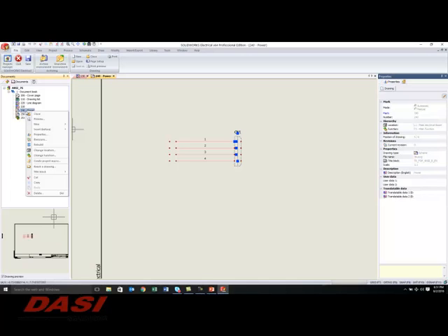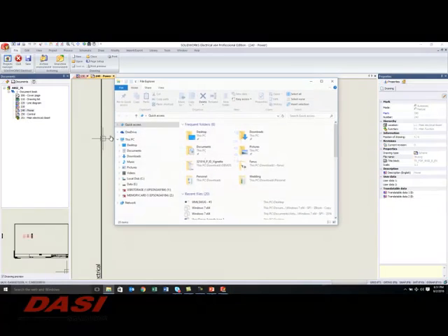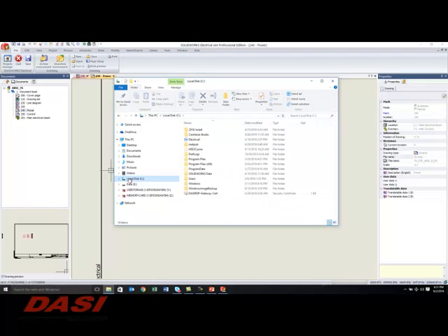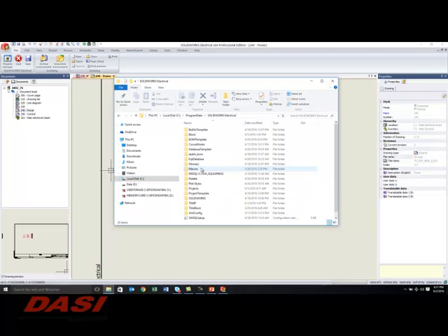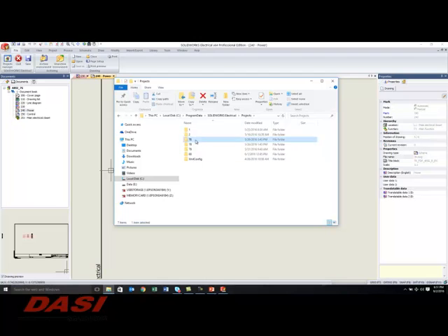sheet for you. Because now if I go back in to that file where I keep, mine is on a local system here, if I go under that program data and go back to my SolidWorks Electrical and back to that project 76, you will see that it has recreated page 36 for me just now. Why did it? Just because you opened it? Because the SQL, yes, the minute I open it again, the SQL knows that that sheet should have been there and will recreate it for me. The SQL is working this way.